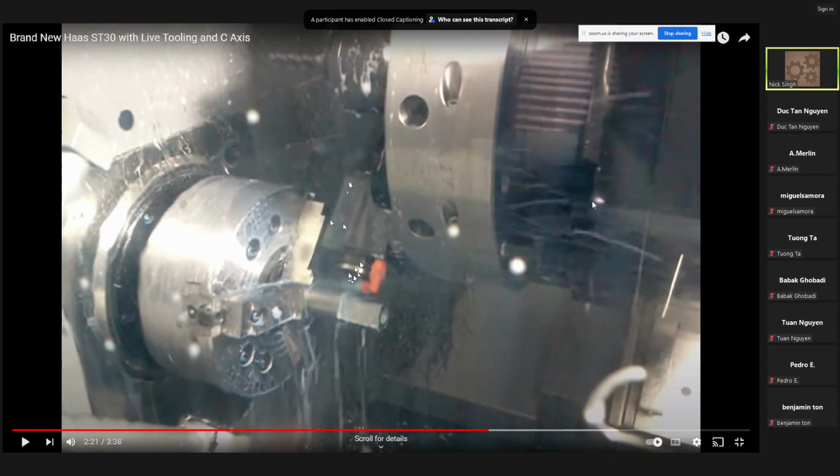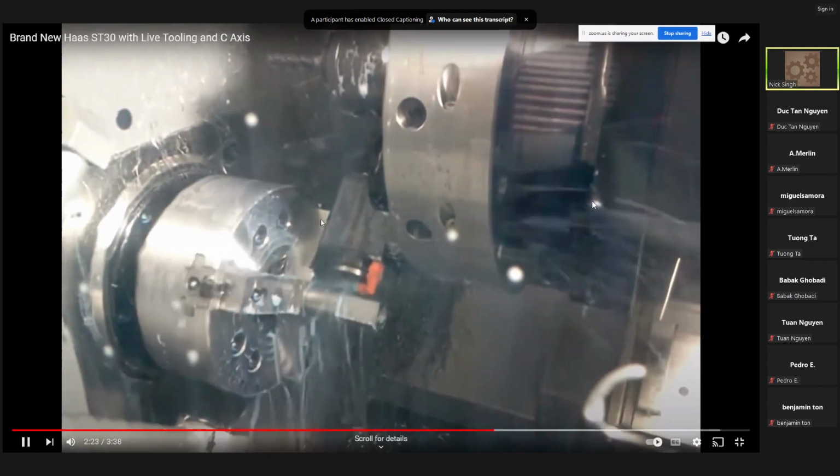It's very close to the spindle. So you have to know what my thickness would be, where the center of the tool is, and how far I can cut from the face into the part, my Z minus, so that your fixture can't hit the jaws back over here. Look at that.